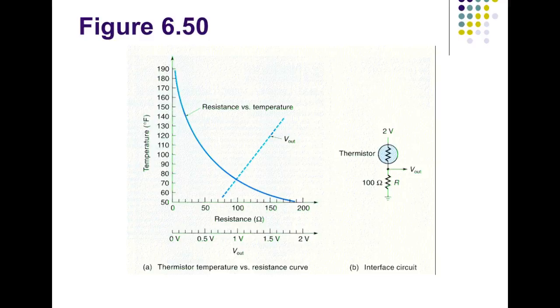So its resistance actually varies with a curve, which like most semiconductors do, by the way. So you can see in this example, the resistance would vary all the way up to 190 degrees, it would be pretty close to 0 ohms. And as my temperature goes down, my opposition goes up, but it's not in a straight line.